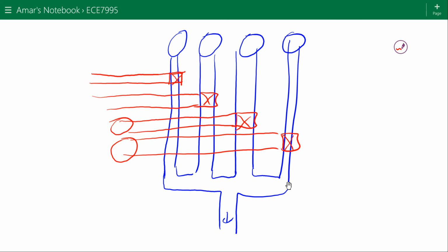Each one of these circles would be an inlet where we could have a syringe to put in a certain gas pressure. If this channel is pressurized, for example, then this channel will be blocked. It won't allow fluid flow. So 4 fluid channels would require 4 gas control inputs. This is fine. This is simple.